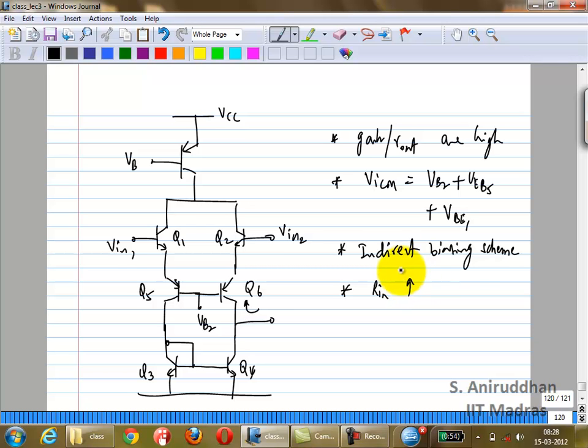When you connect the connectors together, Q1 and Q2, does it work in the same way as the differential pair? Yeah, apart from this, the two sides are almost similar. It's still symmetric. This point will still look like a virtual ground. But the current depends on the base emitter voltage, right? So what's the difference in the base emitter voltages here? Nothing.